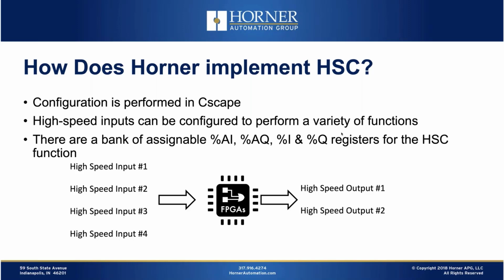And then you have a bank of assignable registers, real-world I/O type registers that are assigned to the high-speed counting function that you can then use for the non-time critical functions, reading the value in the accumulator, how many counts or the time that you've accumulated, whatever the case may be. So this approach of using dedicated silicon means very strong performance with high frequencies supported and a lot of flexibility in the functionality of the function for the machine.